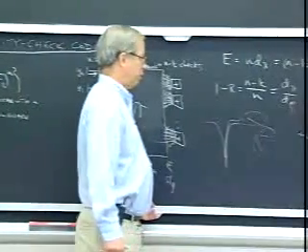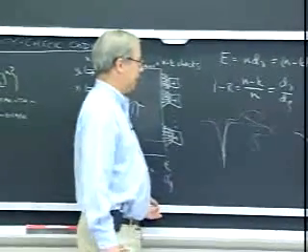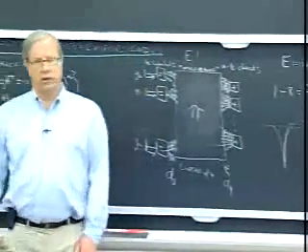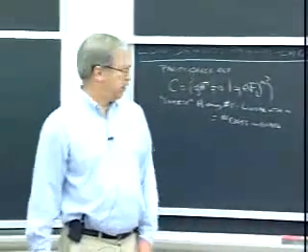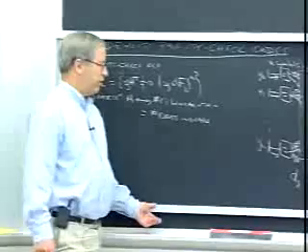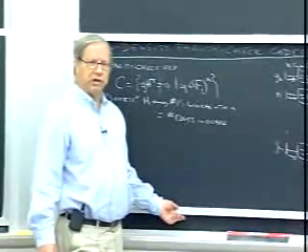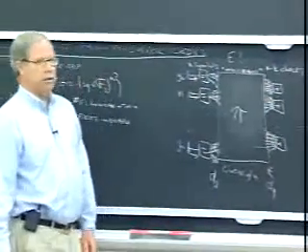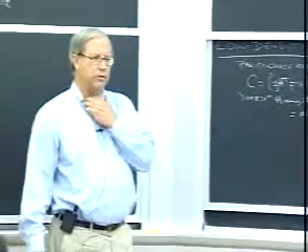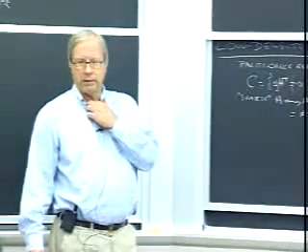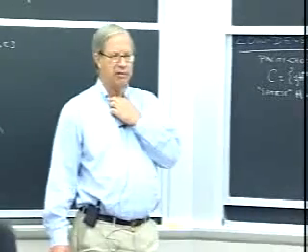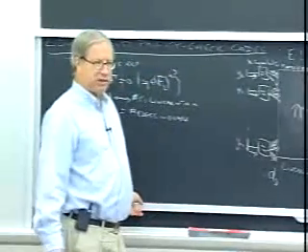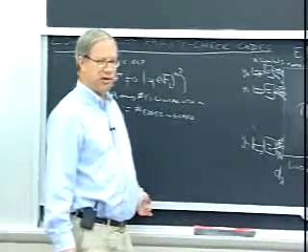that's how it works, and it works great. And as we'll see, even with regular codes, you can get within, in added white Gaussian noise channel terms, about a dB and a half of capacity, and merely by making these degree distributions irregular, this is how Sae-Young Chung got the results that I showed, I think, in Chapter 1, where you get within 0.04 dB of white Gaussian noise capacity, and that's it. So we knew how to get to capacity since 1961 almost. We just didn't realize it.